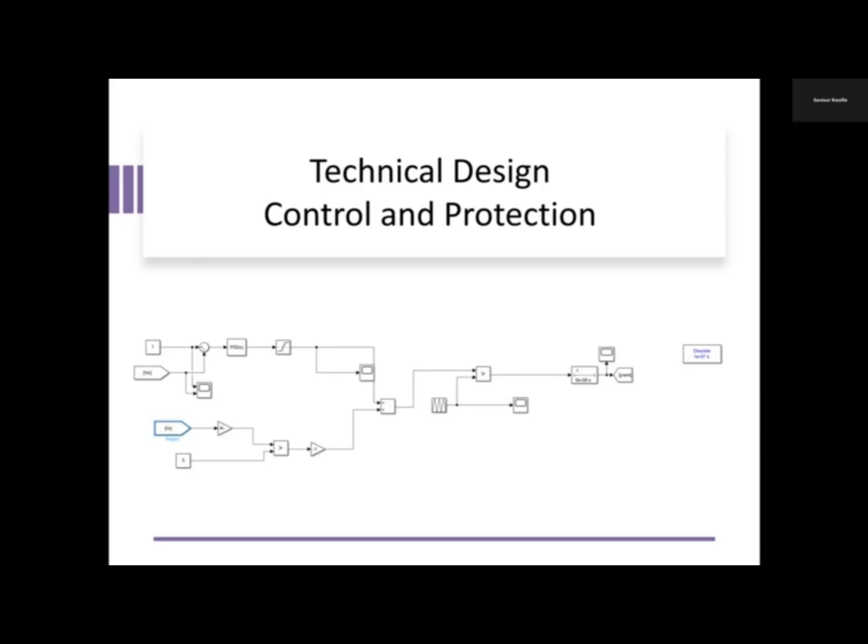The latch can only be cleared through manual reset, ensuring the fault is verified before restarting. Together, the clamp-down and shutdown mechanisms form a two-stage protection hierarchy that preserves converter stability and prevents catastrophic failure during fault or overload events.